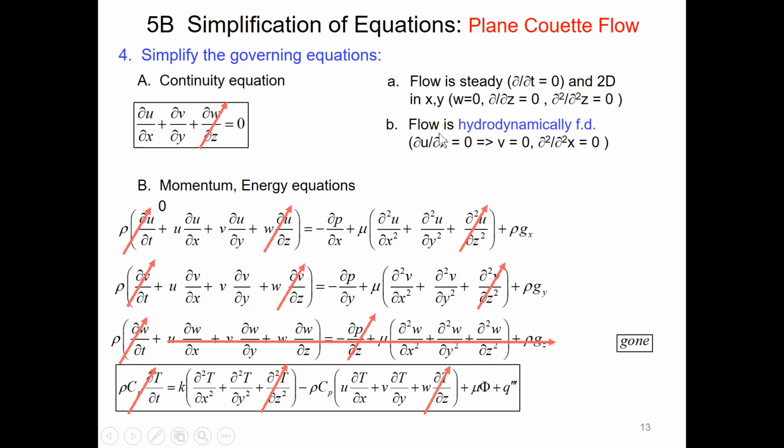B. The flow is hydrodynamically fully developed so that there's no acceleration, no velocity in the y direction. So the continuity equation is satisfied. There's no acceleration.